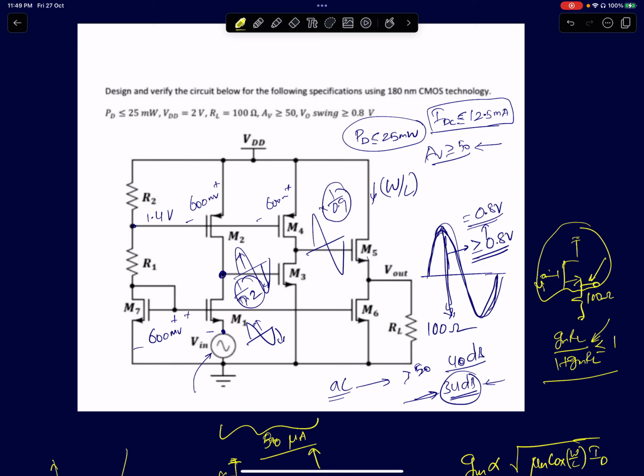You see which node is driving capacitive and resistive loads, and give maximum gain to the capacitively loaded nodes. Conventionally, if you look at audio amplifiers, they will have a gain stage and a driver stage. The final stage is what we call a driver stage. It's driving a resistive load. Generally it's a power amplifier which is delivering some power.